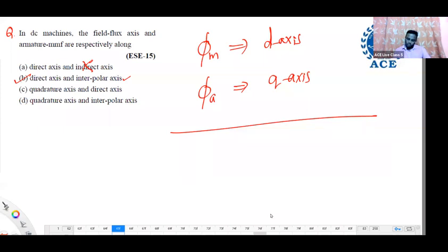Whenever the machine starts, does armature reaction also start? No, because armature reaction takes place only under load condition. Suppose the generator started, that means there is no armature reaction, because it depends on whether load is connected or not. If you connect a load, there is armature reaction. Suppose no load. In no load condition, what is the current in the generator? Very, very small, negligible. Then there is no armature reaction.